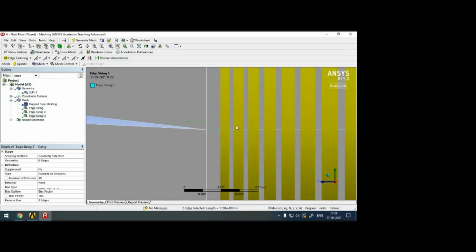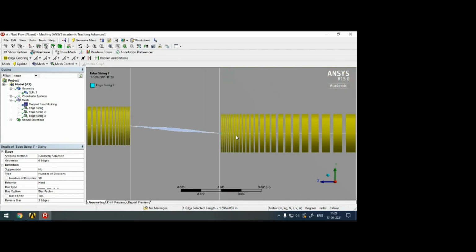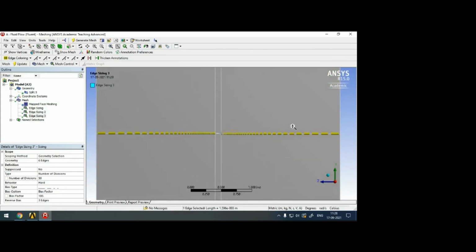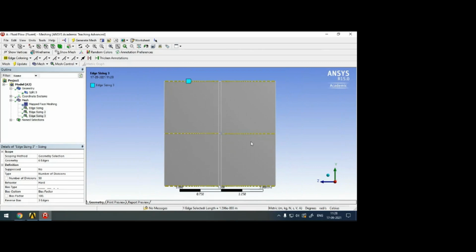The software produces unstructured mesh. The old software, Gambit, could create the structured mesh even if you have 5 splits here but only one line in the above. Here 5 edges, here only one edge, that will create the structured mesh. But in this new ANSYS Workbench, if there are 2 edges here and one edge there, then it will create the unstructured mesh.